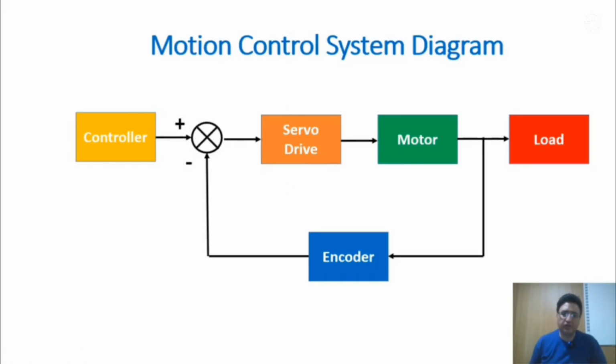For example, suppose we used an S-type drive. This controller can be a pulse generator, creating pulses, and based on the pulses it generates, it can send them to the drive. Since the drive is connected to the motor, it can control the type of movement as well.